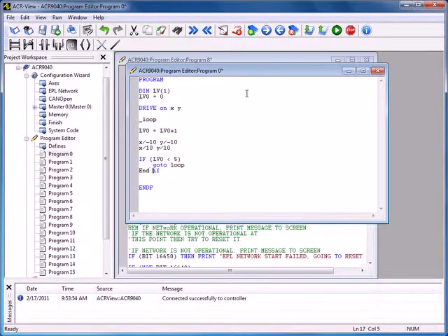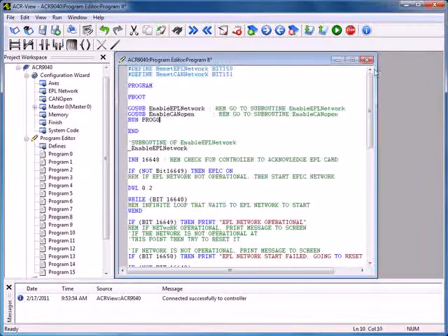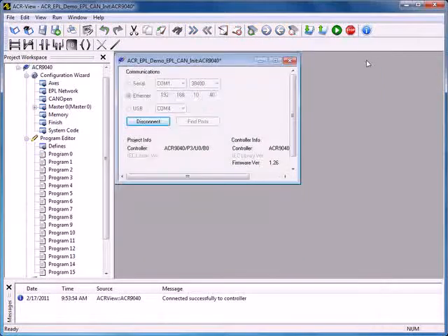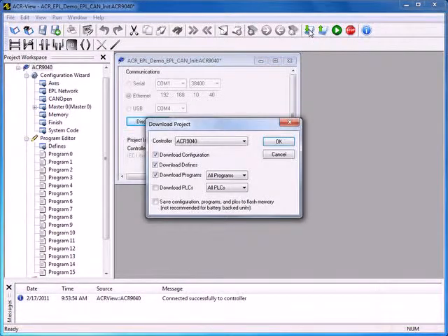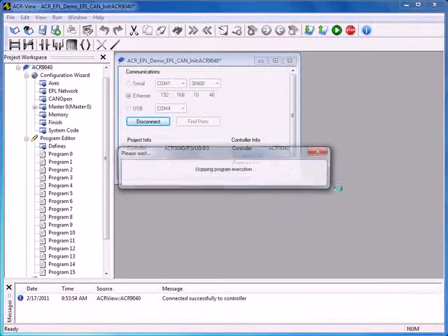List will show me the program that's in here. Now notice I have the line numbers showing up. The reason the line numbers are showing up when I do a list is my processor has bit number 5651 turned on. If 5651 was turned off, CLR 5651, and I do a list, I don't get any line numbers. When we're debugging the programs, it's very useful to be able to see the line numbers, because if we have an error, it's going to come back and tell us what line it's on.